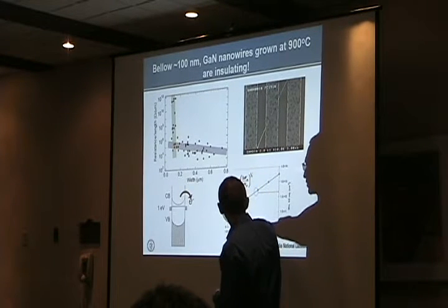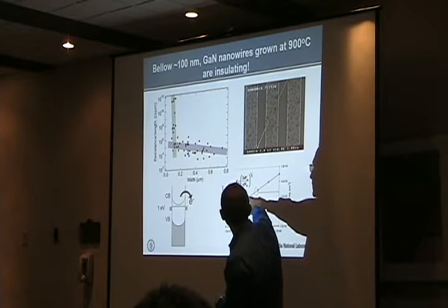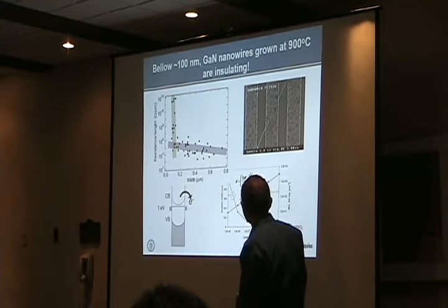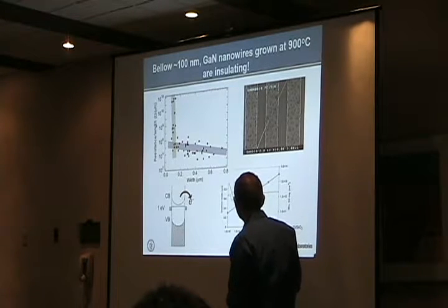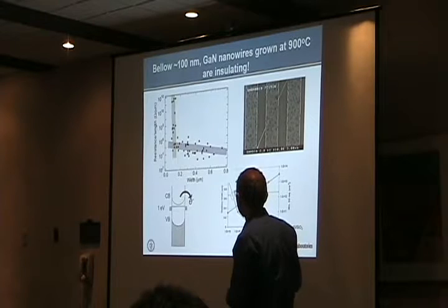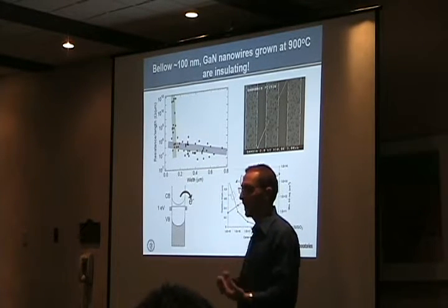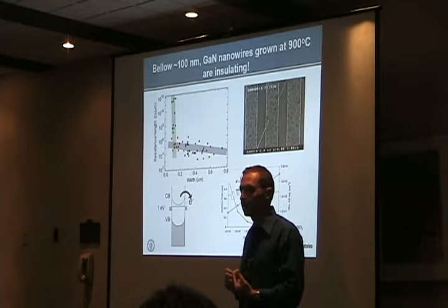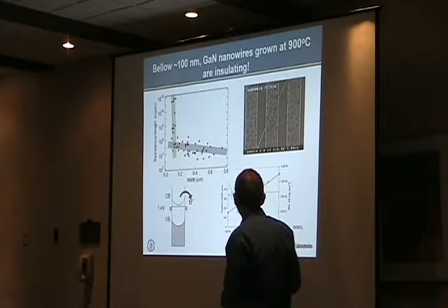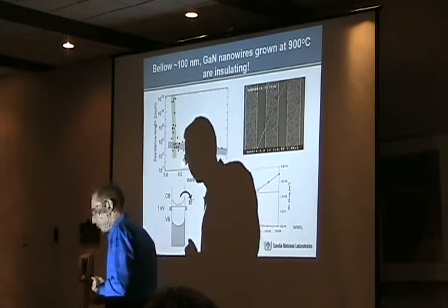And what we find is that at 1e17, if we have a surface state density of 1e12, the nanowire will be completely depleted, and it comes out right at 100 nanometers. Now, of course, this is a very simplistic calculation. I don't know exactly what my carrier density is, but it gives a pretty good feeling that indeed it is very feasible that these nanowires will be depleted.